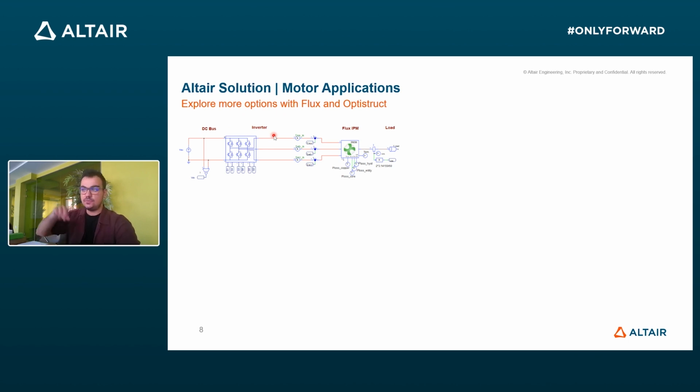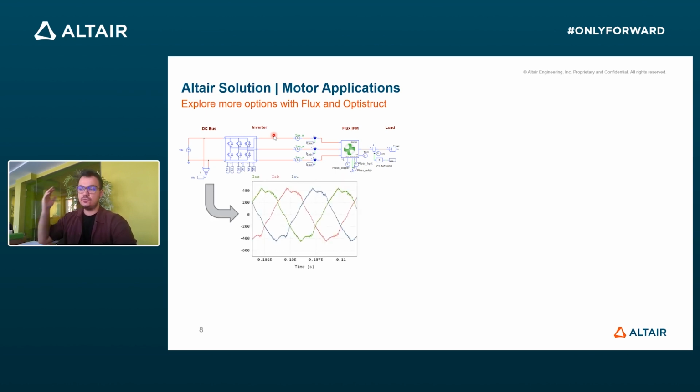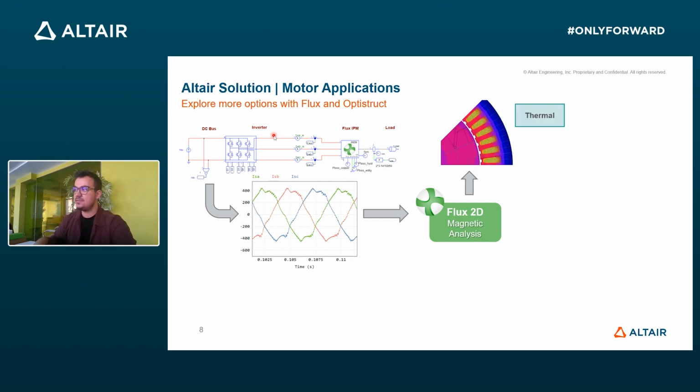And then if you build the controller around this, this is a non-linear motor model, so you will get some harmonics for the supply currents. And those harmonics can cause some issues for the motor. So you can grab those current waveforms, you can feed them back into Flux, and you can, for example, inspect how these harmonics can affect the winding and core losses for your motor.